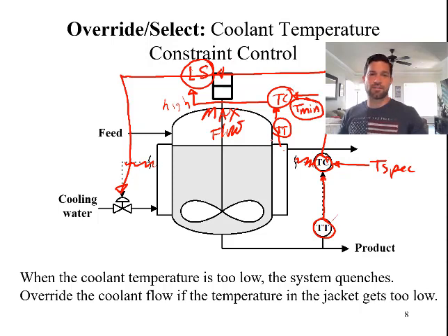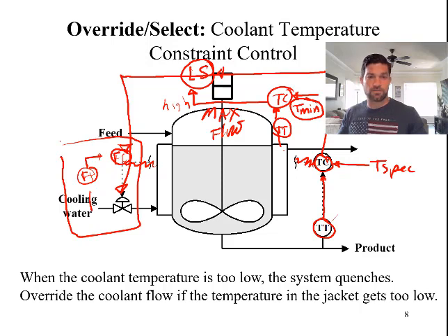There's one more subtle thing I want you to think about with this system, and you can think about this with various types of systems. We talked about this with respect to flow, so I like to put flow controllers here. So I'm going to put a flow controller here. Now in this case, the signals going to the control valve, the final control element or manipulated variable, are both flow signals, so we're comparing high versus low flow signals. This doesn't have to be set up in cascade. This could be set up where both signals are just going to the valve, and it could be an air pressure or a valve position that's the signal.